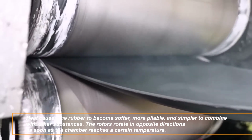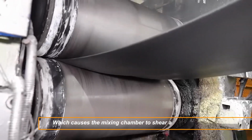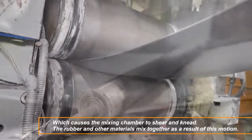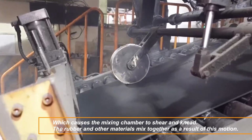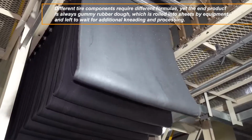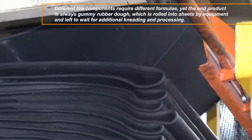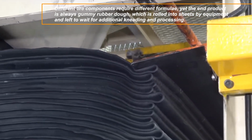The rotors rotate in opposite directions as soon as the chamber reaches a certain temperature, which causes the mixing chamber to shear and knead. The rubber and other materials mix together as a result of this motion. Different tire components require different formulae, yet the end product is always gummy rubber dough, which is rolled into sheets by equipment and left to wait for additional kneading and processing.